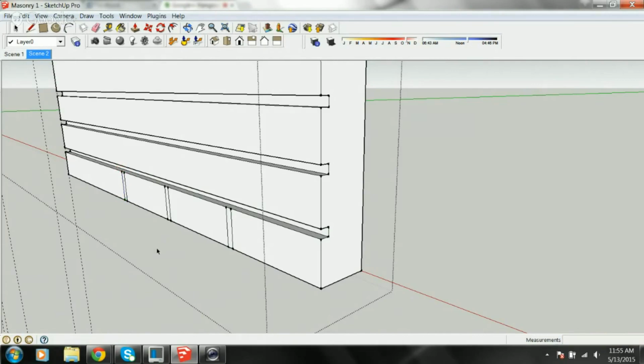Okay. And in the real world, our bricks aren't going to be perfectly stacked in a running bond, typical brick application. So what's 1/2 of 8? 4. So we're going to 3.5 over. Again, I've got to keep in mind that joint I want in there. So now I'm creating. Oops. Now that was just for the first one. So now I type 3.5 in. I want that backspace. Get out of that 7.5. I want to be all the way over here in the middle again.